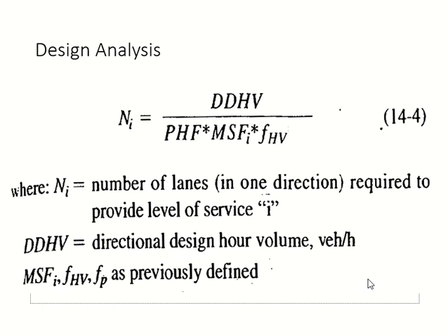So when you design a building, anybody who has taken the design courses, you must have taken the design courses, right? So what is the factor of safety? 1.2 and 1.6, right? So that means what? The applied load is how much less, or the capacity is how much more? 20% and 60%, right? We don't say we apply the entire load and the capacity is still 90% or 80% higher than that, because that will be too expensive. Your building will be too strong, when you don't need it. You don't need to make it this way. Clear?